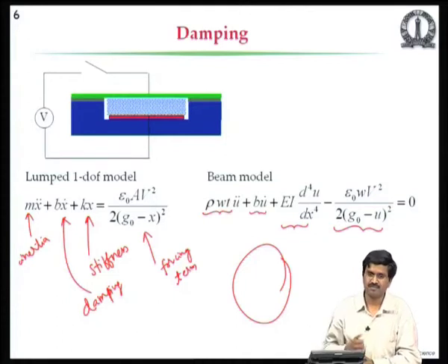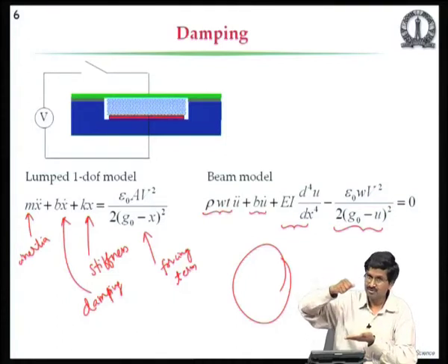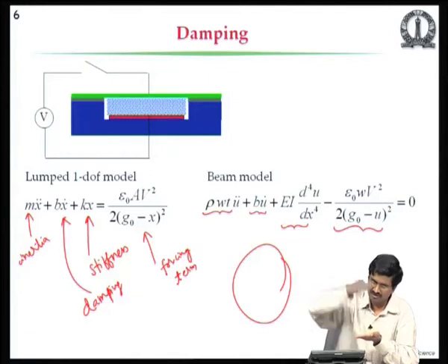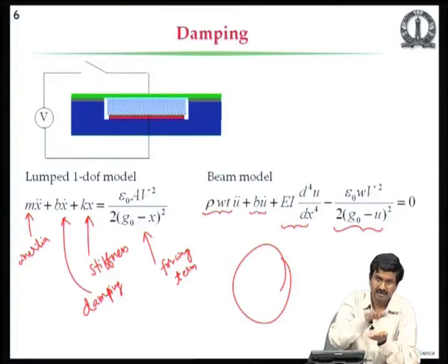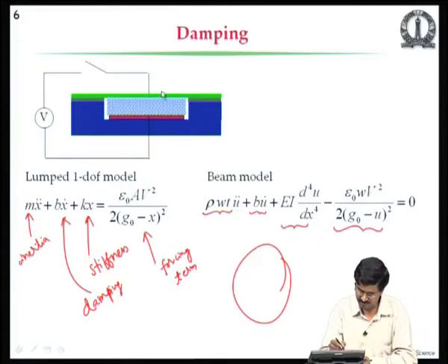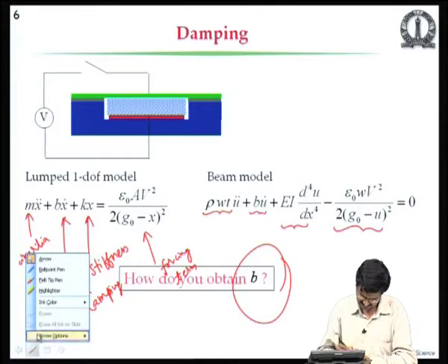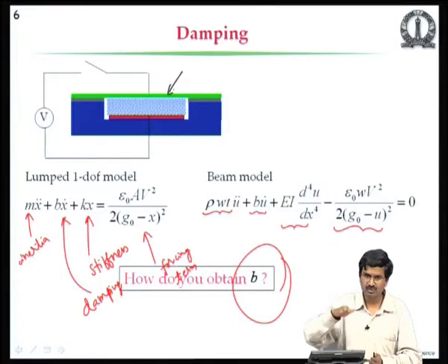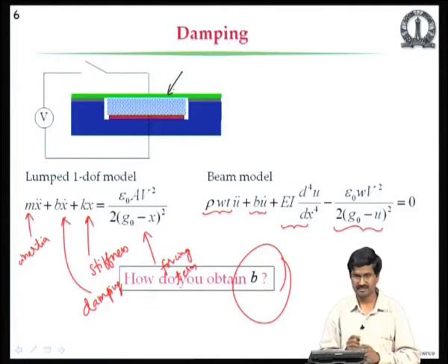Imagine a cycle pump. When you try to push the pump slowly, you would not feel as much resistance from the fluid as you would feel if you were trying to pump fast. The faster you do it, the more resistance due to viscosity that you feel in a cycle pump. Similarly, here when this top plate or a beam over here moves slowly, you would receive much less damping force or fluid force as opposed to doing it very fast. We will analyze that.